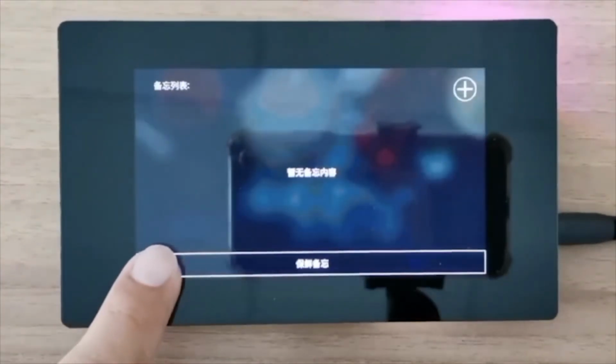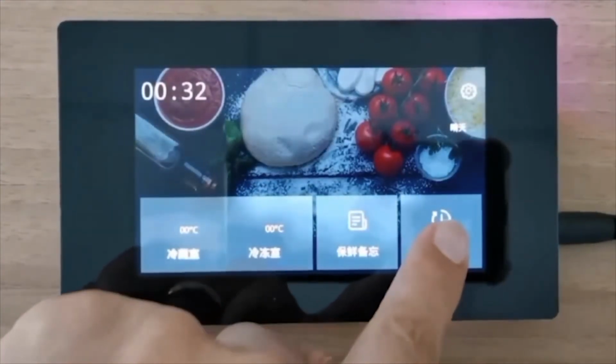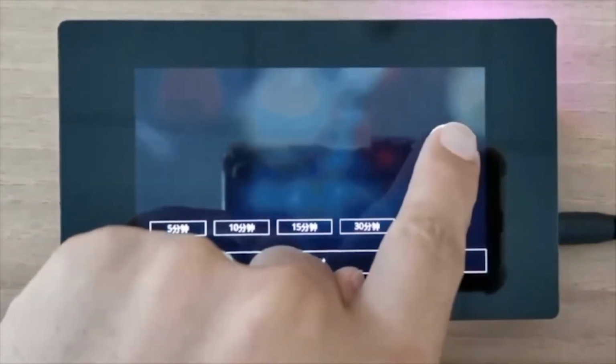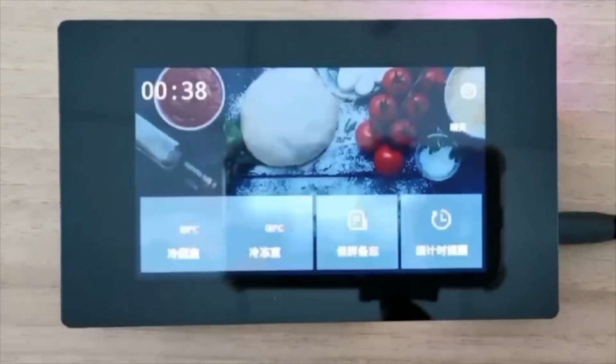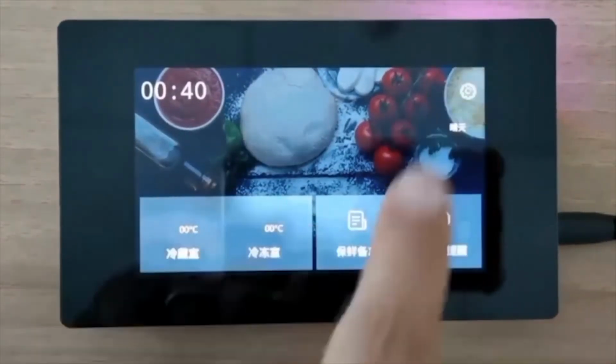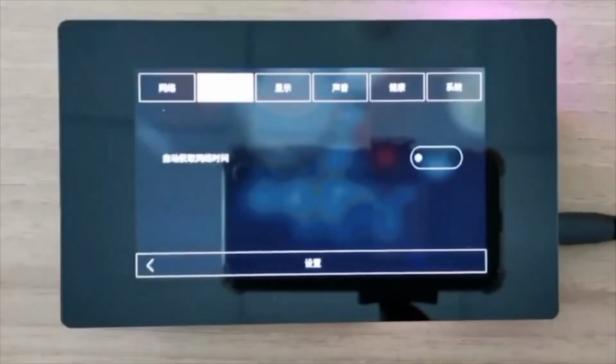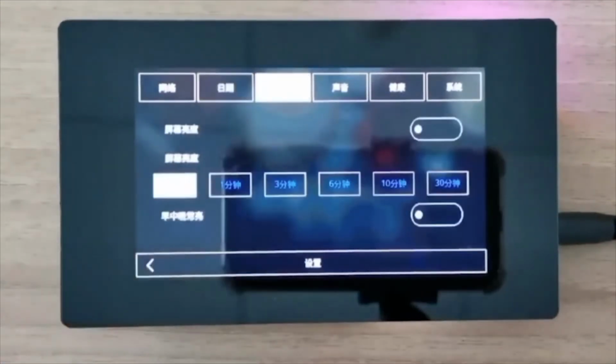With an embedded simplified GUI framework running on the on-chip MCU, it can support button, character, diagram, table, and slide operations. The FPGA logic is mainly used for display memory management and image processing such as alpha blending for the transparent effect.